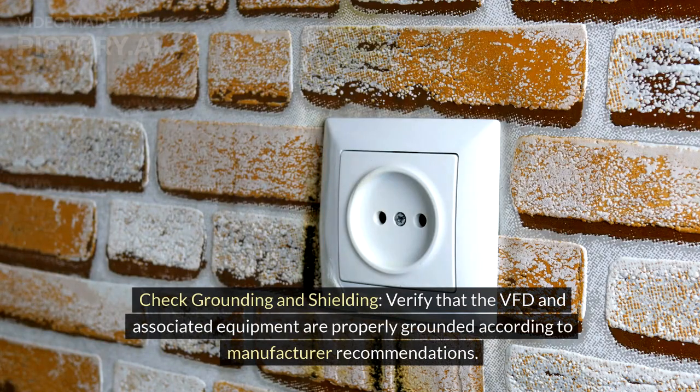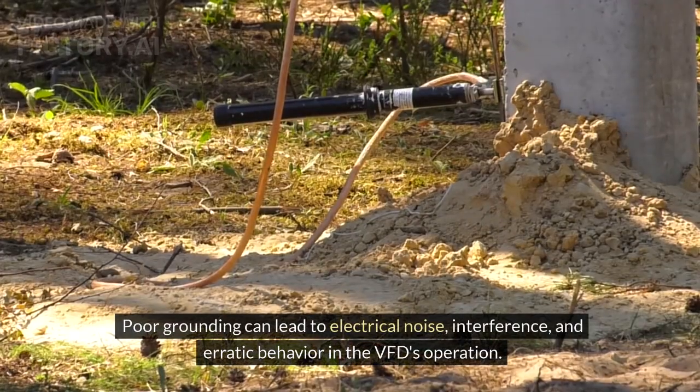Check grounding and shielding. Verify that the VFD and associated equipment are properly grounded according to manufacturer recommendations. Poor grounding can lead to electrical noise, interference, and erratic behavior in the VFD's operation.